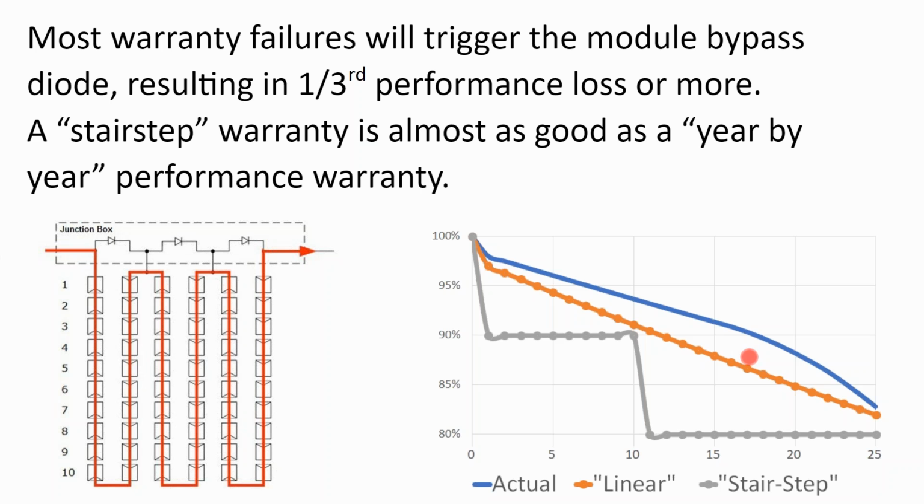We got an audience question. Is the performance affected by workers stepping on the panels during installation? The answer is yes. That's the danger of the installer getting too comfortable with a solar panel: these failures can occur at the microscopic level. So you could have a solder point pop and you really can't identify it with the naked eye.